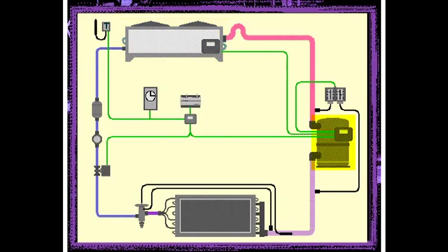The compressor and the condenser fans operate simultaneously. It is the outside air that absorbs the condensation heat. The function of the inverted U-trap located at the condenser inlet is to reduce the hammer effect caused by the sudden arrival of a mass of refrigerant in the condenser. This usually occurs when the compressor starts up. The inverted U-trap also holds back the liquid refrigerant and prevents it from returning to the compressor when the compressor is off.